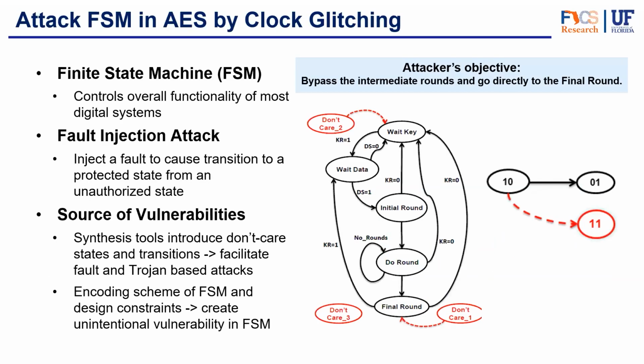So we show some applications of these faults on different designs. For example, here we have an AES design. We are showing the finite state machine of the design. That finite state machine usually has 5 states, based on one of the implementations that are accessible from open code.